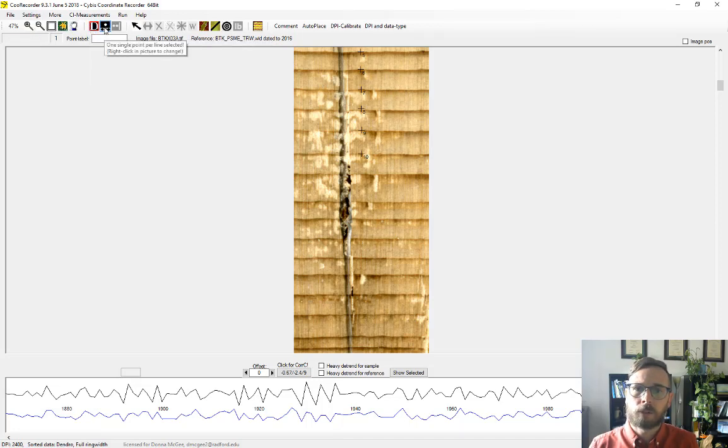And instead of this single dot, if I toggle that, it'll show the 3 dots. What that allows me to do is, when I put in this next point, I can click it, and then I can shift my pathway over. The advantage of this is that you can shift your pathway and it won't measure between those two shifting points. Now I can continue down through this pathway with another section of auto place,